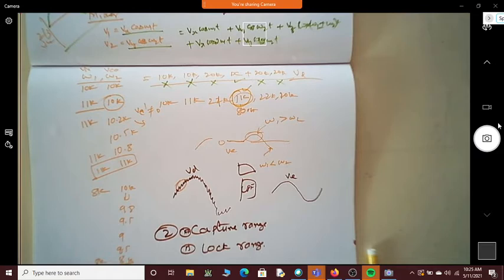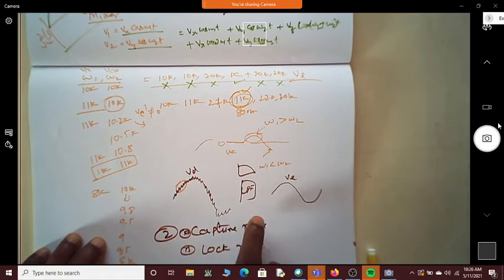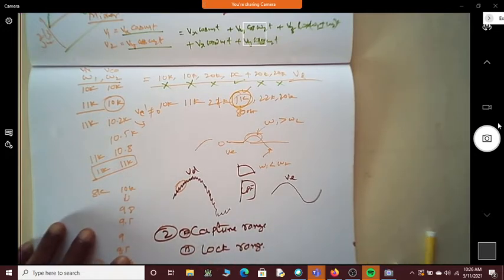It's very important that I should first capture you people. So maybe in the beginning, I just ask everybody to join. And how long you'll be there with me depends on whether the topic is interesting and you are interested in it. Trapping will be interesting, but if you're not interested, then you'll just lock out of that. Here the point in the case of PLL is first I should capture the signal and then keep locked to it. So what are capture range and lock range?